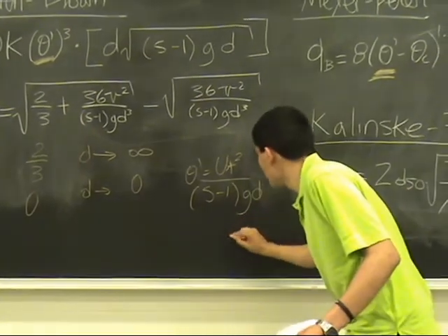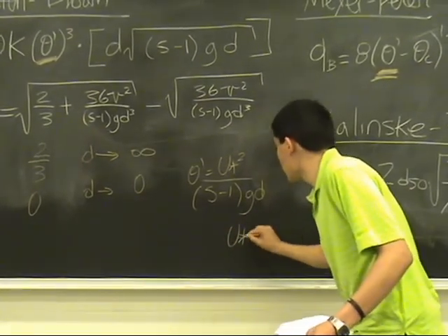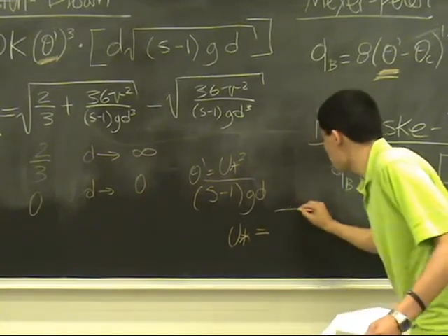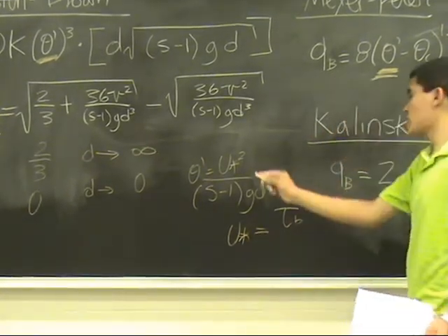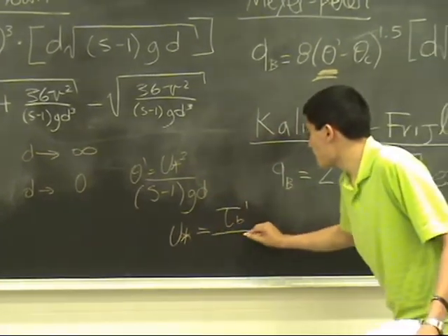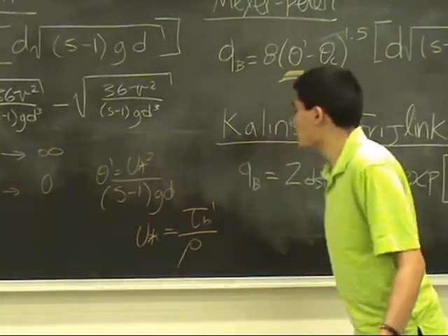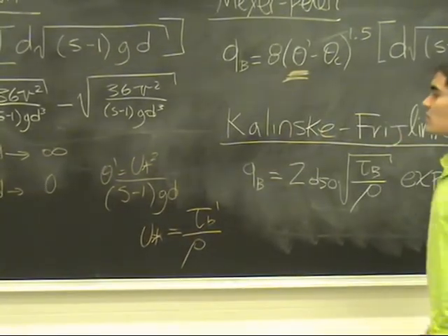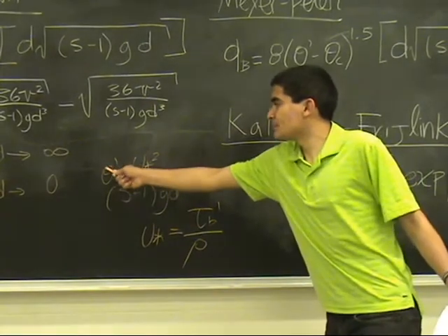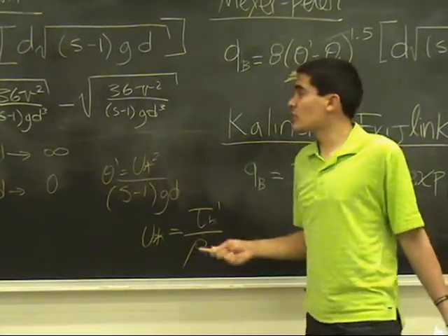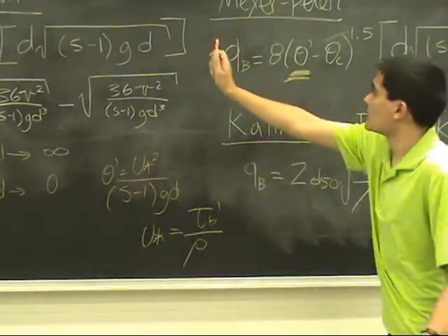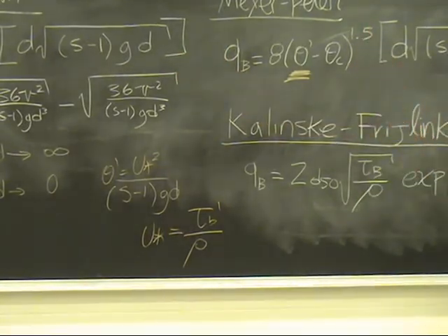And the friction velocity squared, what is that? Well, that is just the effective shear stress we calculated from before divided by rho. So generally, this term is very big relative to the critical shear parameter. So we use it in Einstein and Meyer-Peter.